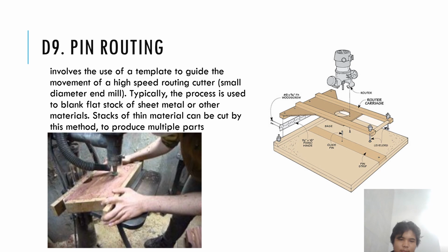and then dished out the tray with this setup, the 1 1/4 inch diameter router bit with radiused edges, and then a 1 1/4 inch diameter pin that I made from aluminum that goes in the table. Another thing I did earlier today is I made this little dust shield and hand shield to keep hands away from the bit and also try to collect some of the dust that's thrown by the bit.